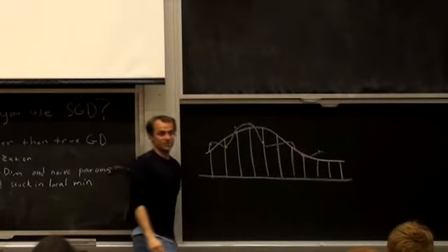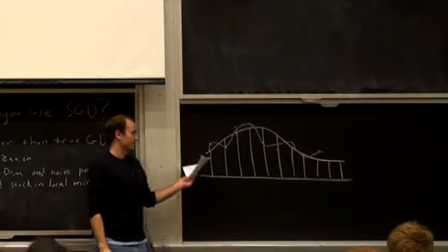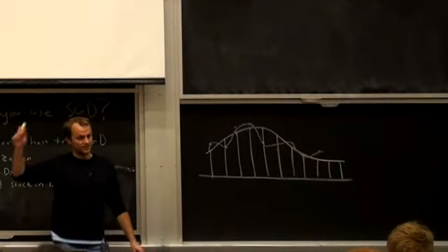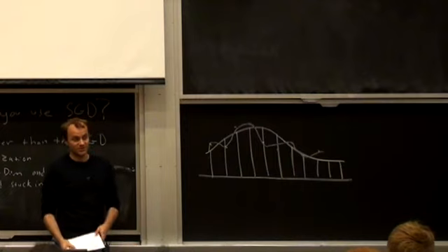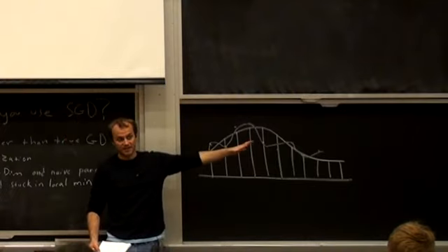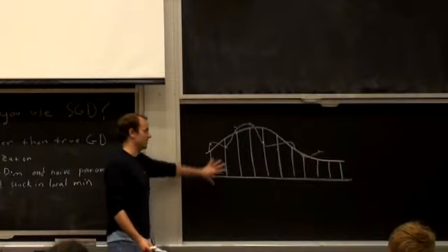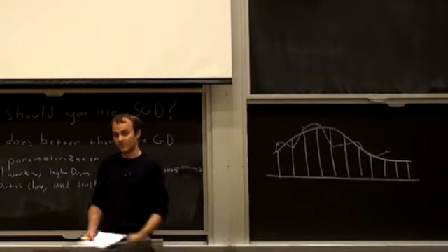Now, your physical system is going to smooth that out. It's going to filter it. You're not going to execute something like that necessarily. But it's very unlikely that that's the right kind of policy. It's very fine-grained and doesn't necessarily make sense. So if you assume you're going to have something smooth, it's nice to use something that's always relatively smooth. Like if you were to use fewer points to parameterize a spline, that could be a win. So that's what I mean by a good parameterization: something that ideally captures the kind of behaviors you want in your system.